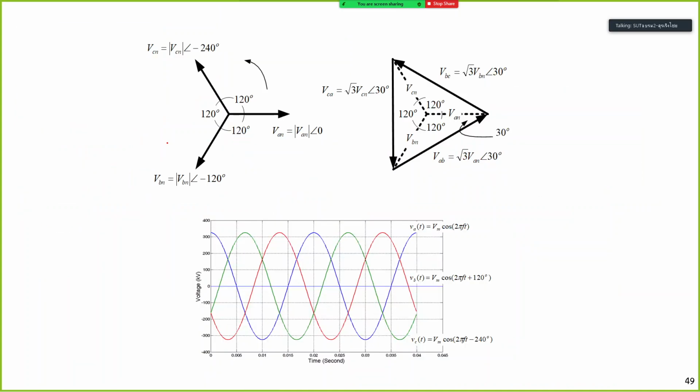When we solve the three-phase electrical system, we have two types of voltage reference. First is the voltage of each phase, and next is the voltage in between the phases, for example the voltage between A and B. Each phase has its own sinusoidal signal. For example, this is phase A, and A to the reference, or neutral in the three-phase circuit, can also be represented in phasor form.